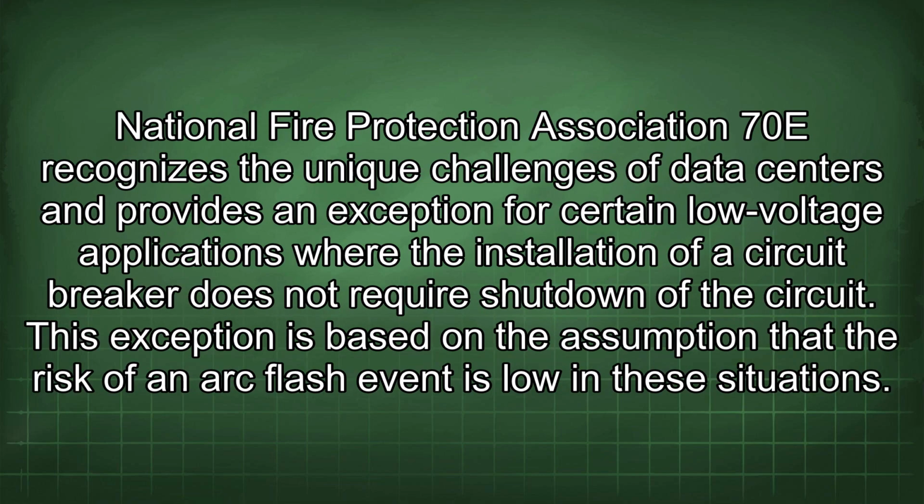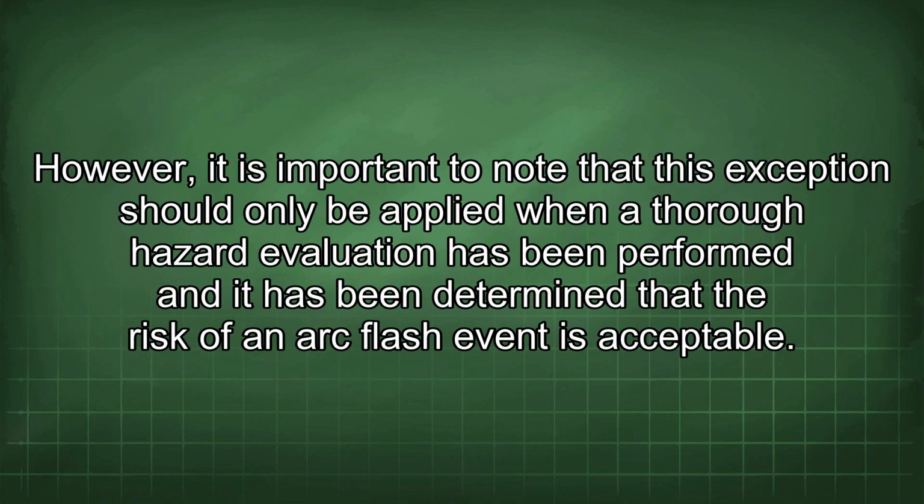hazards. National Fire Protection Association 70 recognizes the unique challenges of data centers and provides an exception for certain low-voltage applications where the installation of a circuit breaker does not require shutdown of the circuit. This exception is based on the assumption that the risk of an arc flash event is lower in these situations. However, it is important to note that this exception should only be applied when a thorough hazard evaluation has been performed and it has been determined that the risk of an arc flash event is acceptable.